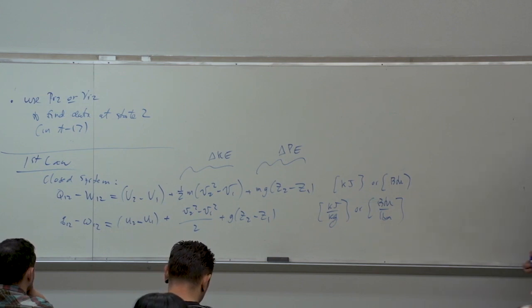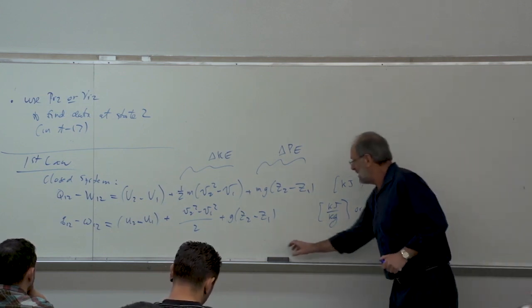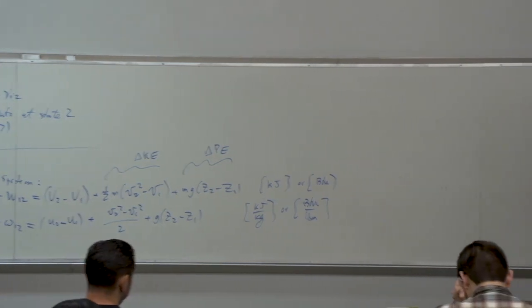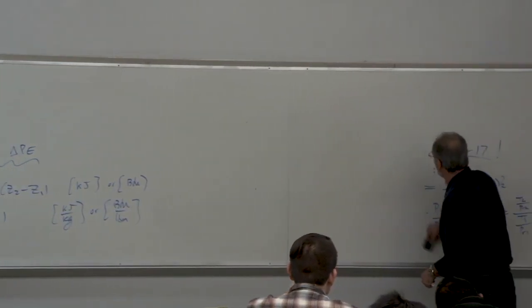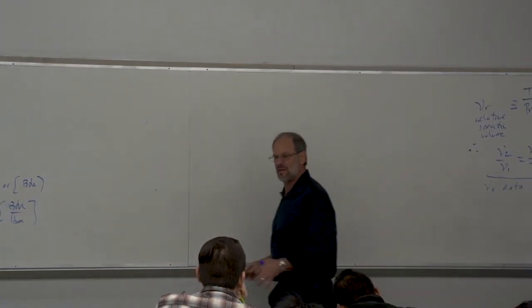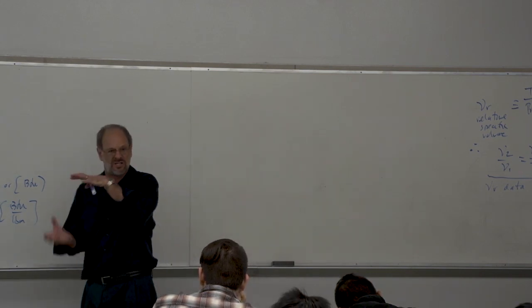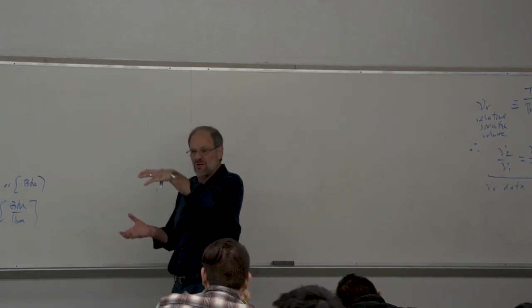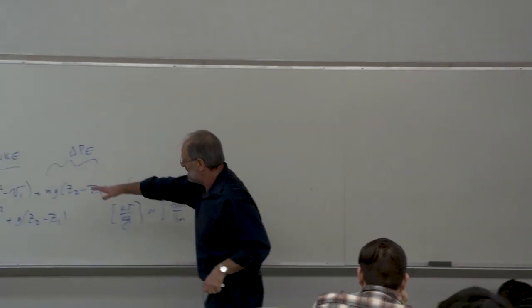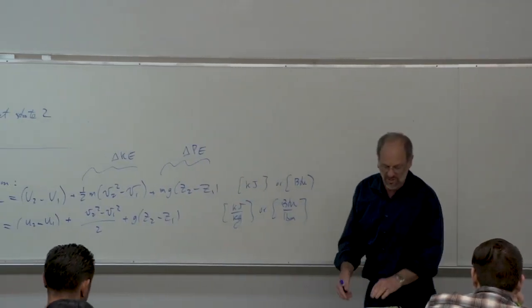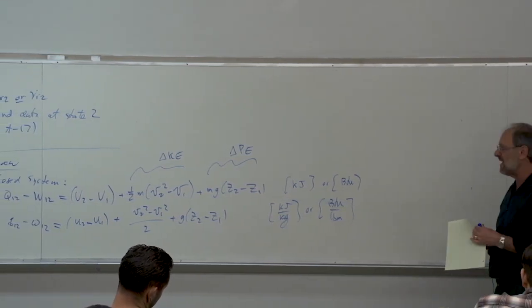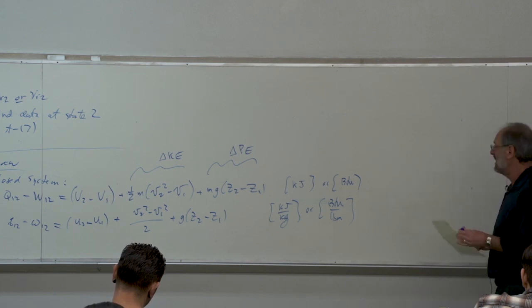So these are the equations that would apply for a closed system. Now keep in mind that as we begin talking about cycles next week, we will start with closed systems. In fact, what we're going to start with first next week is the various cycles that apply to internal combustion engines, which are really just piston cylinder devices, right? It's a piston cylinder device. The mass is fixed. They're closed systems. So those are the equations we might use as we analyze engines or processes involving piston cylinder devices that are within engines.